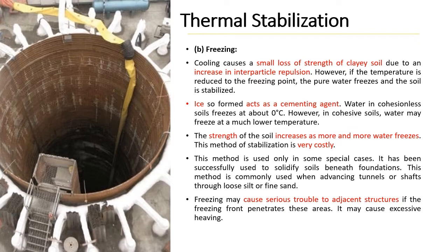It has been successfully used to solidify soil beneath foundation. This method is commonly used when advancing tunnels or shafts through loose silt or fine sand. Freezing may cause serious trouble to adjacent structure if the freezing front penetrates this area. It may cause excessive heaving, which is the ground moving upward, usually associated with the expansion of clay soil, which swells when wet.